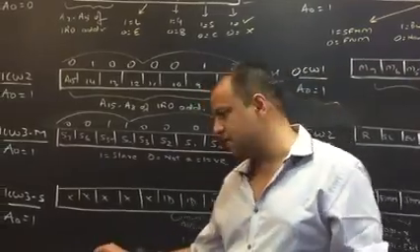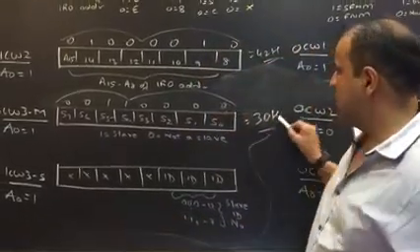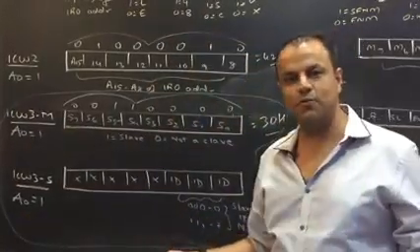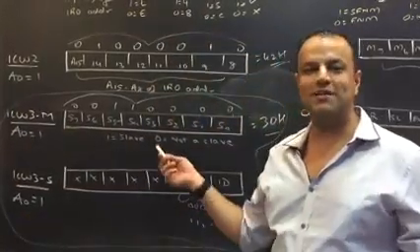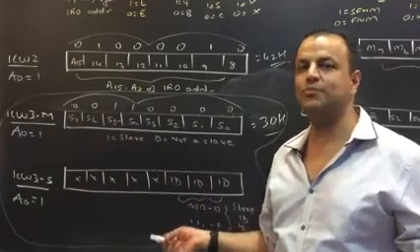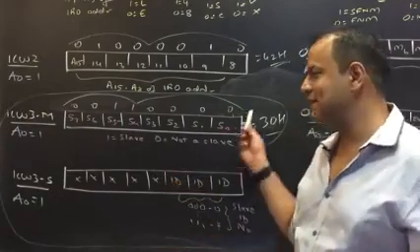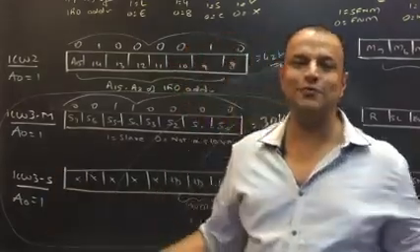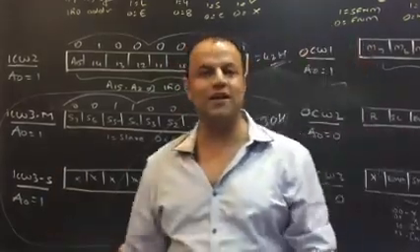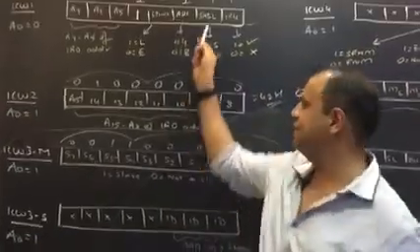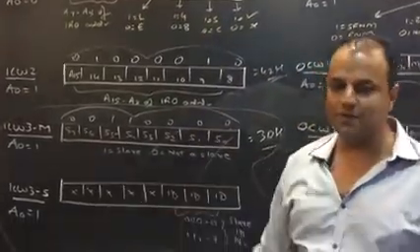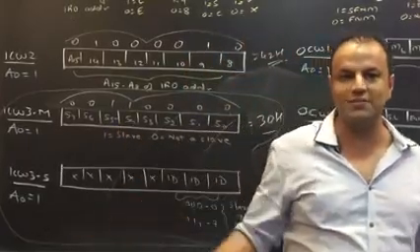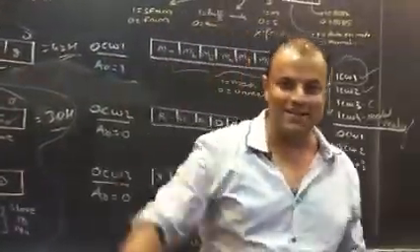Also, if you're a deep thinker, what did you understand? Look at all this information and tell me, all this information is about what? Cascading. You're telling the master where the slaves are, and you're telling the slave what its ID number is. So all this information is about cascading. That is why ICW3 is given only for cascaded 8259s. For a single 8259, all of this is meaningless information. Once you've told 8259 it is single, there is no scope of giving ICW3. Even if you give it, it won't be accepted, because all this information doesn't exist for a single 8259. Tell me, did you understand?